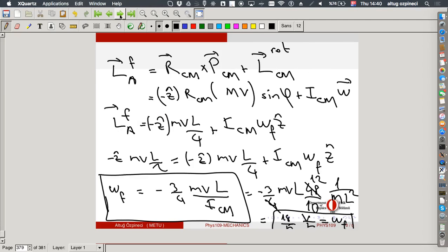Well, when I'm writing my equations, here I said let omega be omega in the z direction. This omega is not the magnitude, it's the component in the positive z direction. So this number just turned out to be negative, which just told me that it is rotating in the clockwise sense. So before solving, I don't even need to make any assumption on the direction of rotation. I can just leave it as arbitrary. The sign of this one can be arbitrary.